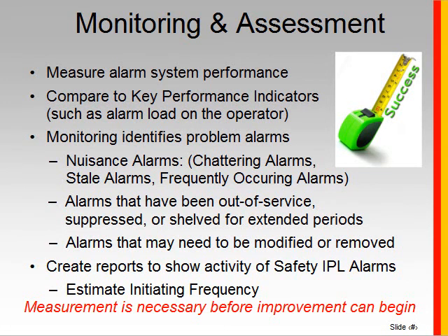We also need to measure, of course, the alarm system performance as the key means of determining or analyzing whether we're going to get the PFD from the system that we want. And we want to compare key performance indicators like the alarm load on the operator. That's one of the key elements we want to do. But we can also identify the alarms that are being problems. Nuisance alarms we can identify, chattering alarms, stale alarms. In other words, we can analyze and see which symptoms or which issues we have and what are the particular alarms that are causing them, so that we can go back and fix them or redesign them through the rationalization process, thus creating a continuous improvement process.